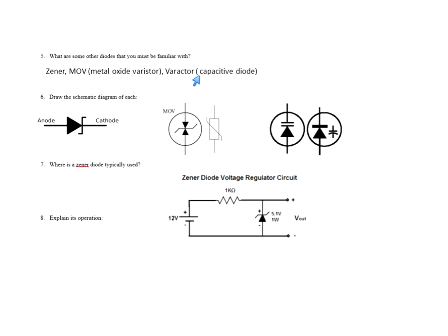First of all, here are the schematics. Here's a Zener. It has kind of like a Z over here. This is actually backwards; it should look like a Z. Anode, cathode, that's a Zener. Here's an MOV. It looks like that. Sometimes you see it pictured like this. Here's what we call a varactor diode. A varactor diode is a capacitive diode. When I look at it, there's a capacitor in the cathode, or sometimes the capacitor is drawn over to the